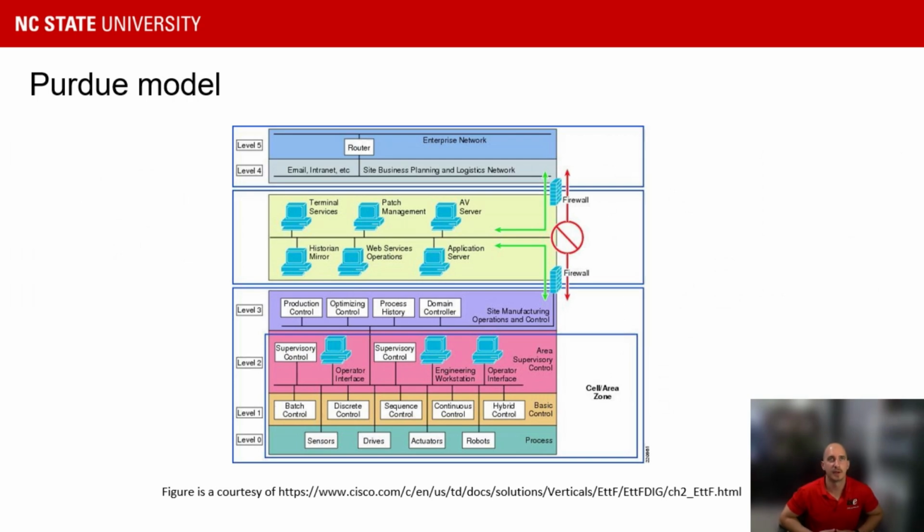Most modern manufacturing processes follow the reference model for computer integrated manufacturing, also known as the Purdue Model. The IIoT architecture does not fit this model, especially with big data and machine learning applications. The Purdue Model prescribes 5 layers that separate OT from IT. Levels 1 to 3 are located on the factory floor and are not connected to the internet. The demilitarized zone, or DMZ, at level 3.5, performs the cybersecurity function and air gaps the OT from IT.